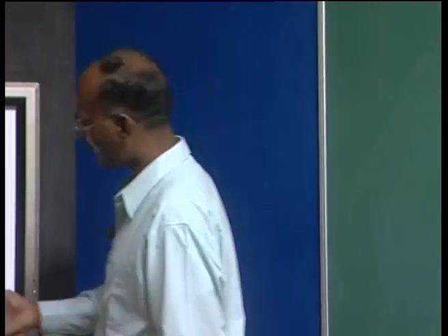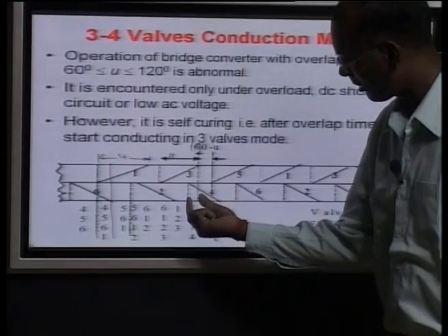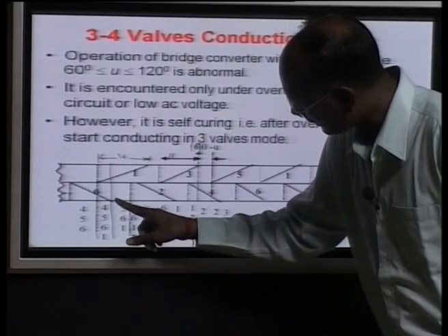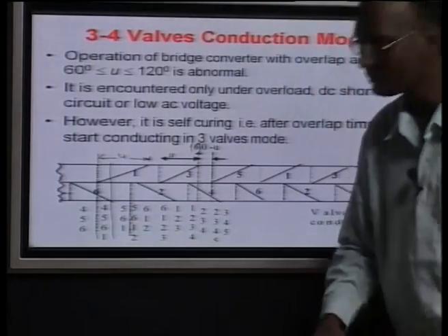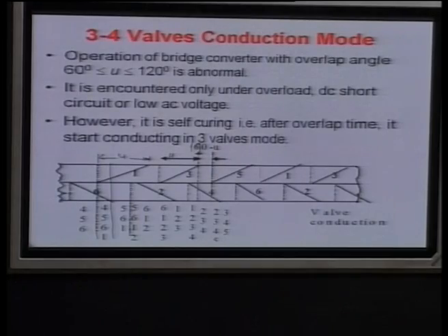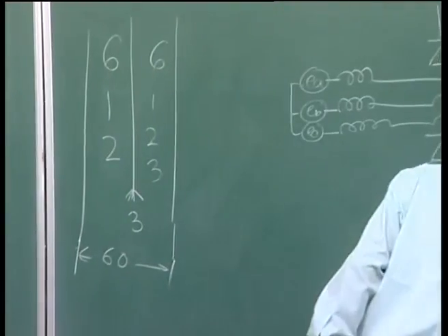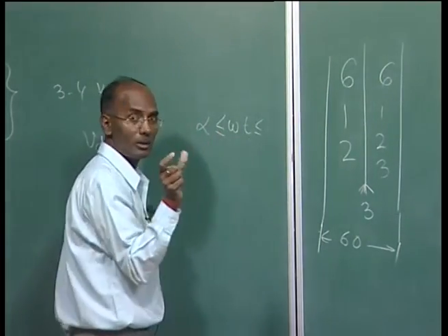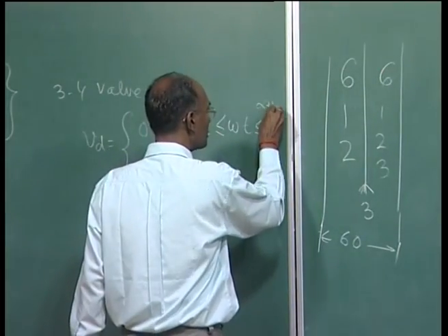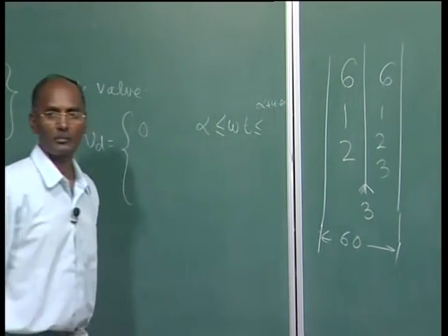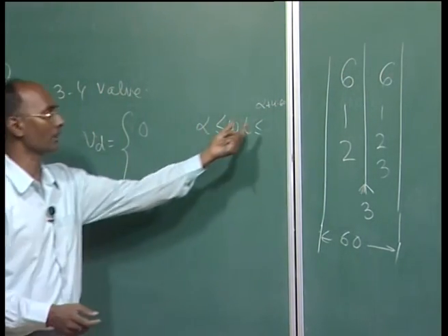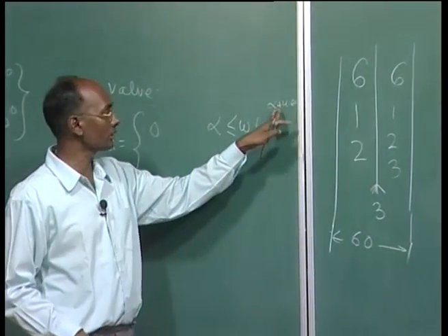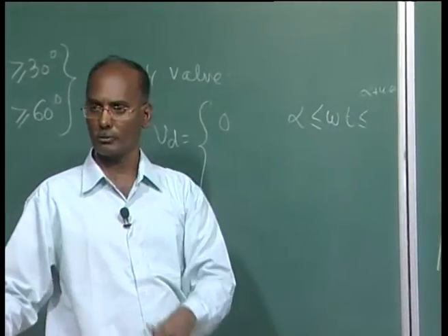When the 4 valves are conducting, in this period, it is u minus 60. Yes, so here it is the u minus 60 duration. So, it is alpha plus u minus 60 degrees, because we are delaying. The period here will be u minus 60 degrees, that is true. So, if u is 75, then it is 15 degrees, and so on.